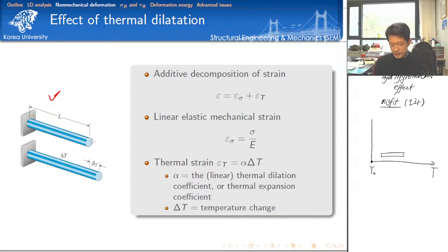This is the reference temperature. Typically the reference temperature is 25 degrees Celsius, and this temperature is assumed as the reference, called room temperature. And then let's try to measure the strain change by the temperature change. What you can see is an almost linear relation, typically in the range where the temperature is less than 100 degrees Celsius in the case of concrete.